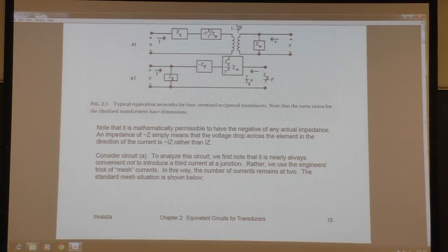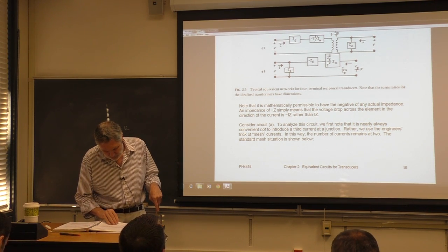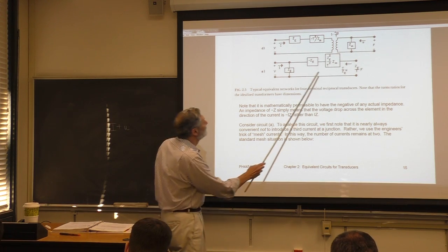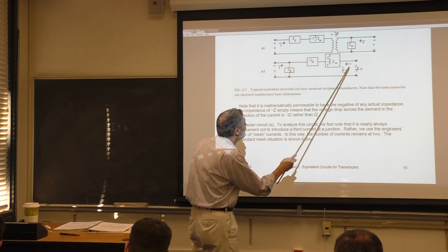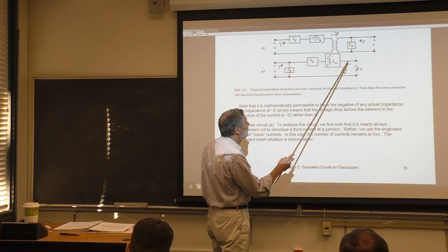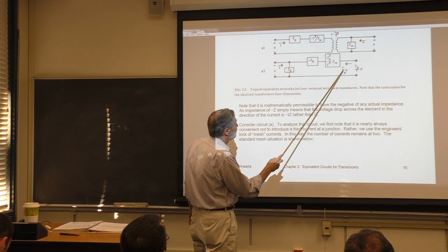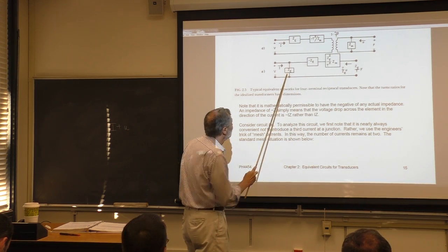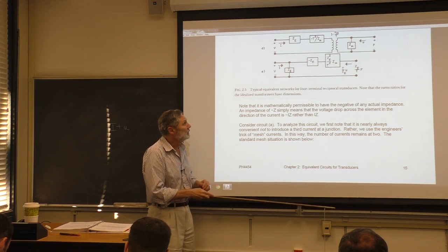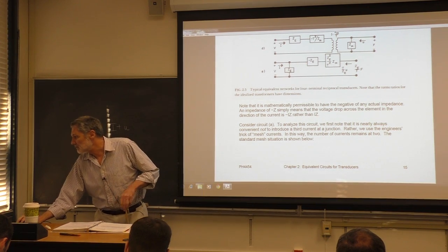All right. Now let's go back and do the same thing. Let's look at the right loop now. Here we only have two loops. So we do the same thing. This voltage here, this quantity here, must equal the sum of the drops along here. So I just add these two impedances, multiply by the current. That's the voltage drop here. And then I add the same voltage drop here that we had before. I set the sum of these drops equal to that. And here's what we get.